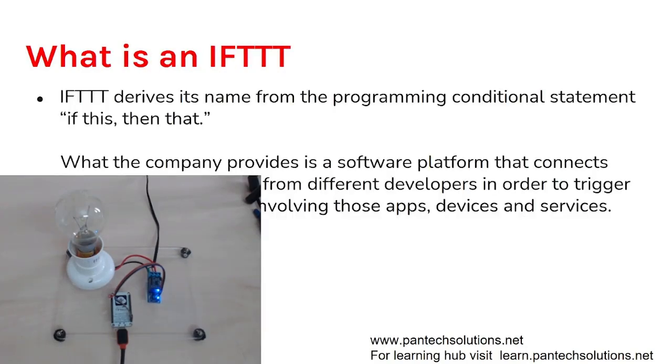Okay. So you could use IFTTT for automation. IFTTT stands for if this, then that. You usually have a webhook, and this webhook has to be copied from the Blynk app. A webhook can access a website without username and password by using the REST API, and you could access the data from the account.